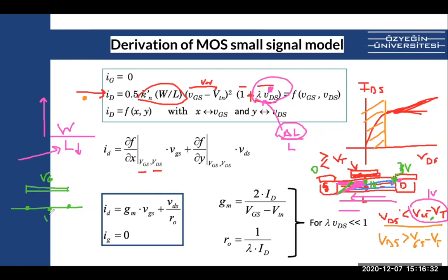So if I have the pinch point at VGS minus VT, and let's say the source is 0, so I am always writing VG, the difference between these two voltages is VT. VGS minus (VGS minus VT) is VT, right? That's what you need to create electrons here.